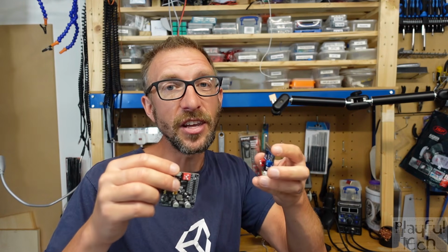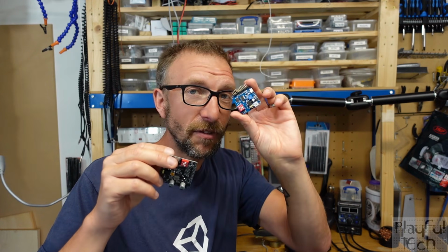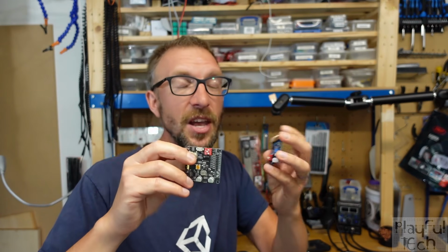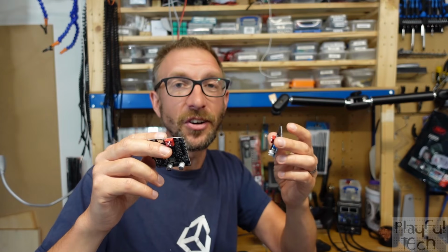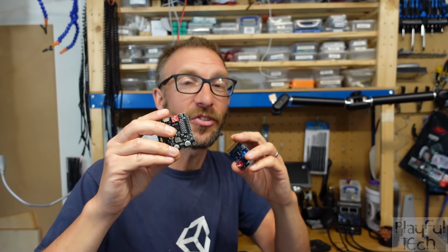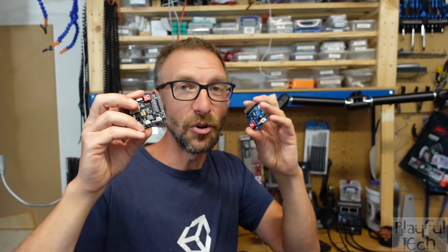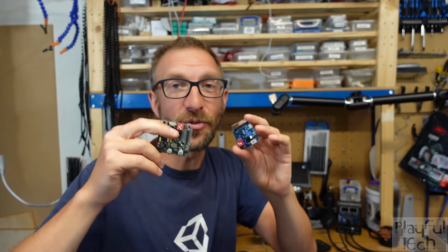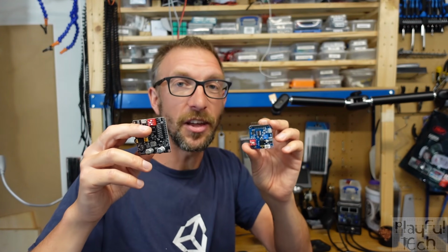And those are all great boards in their own right, but if I were to recommend an audio board right now for you to integrate in your small electronics projects, I would recommend either the 5W or the 8F if you have moderate audio requirements, or if you want to go for something much louder, much bigger, go for the upgraded versions that have the 20-watt amplifier. And you can choose whether you want to use the flash or the SD card versions. Based on my very limited test, I would say the SD card version is more flexible, it's actually a little bit better performing, and they cost exactly the same amount. So for all that additional storage, I would say it's probably worth it.